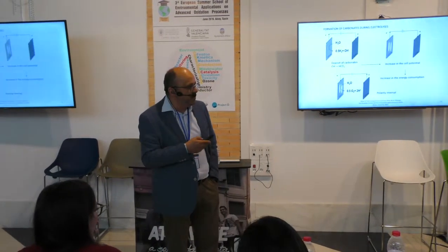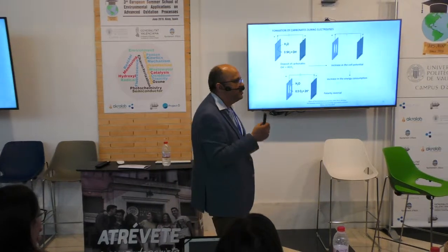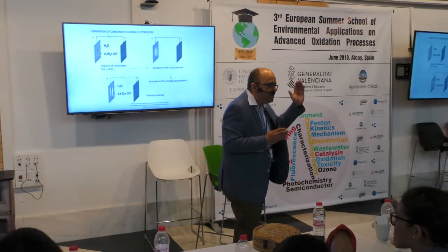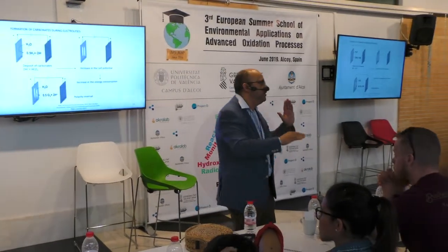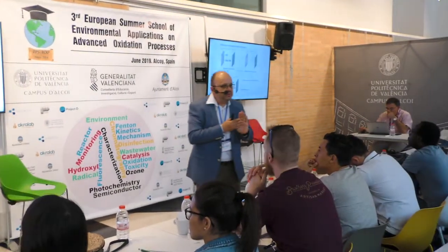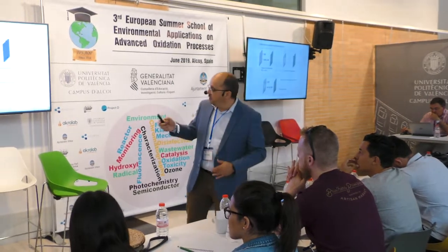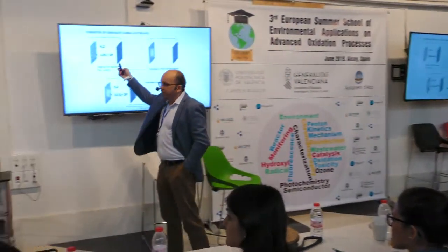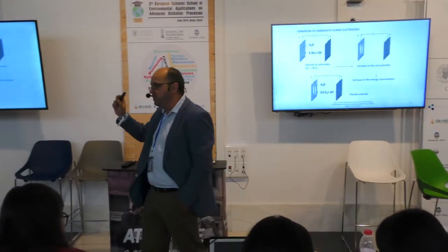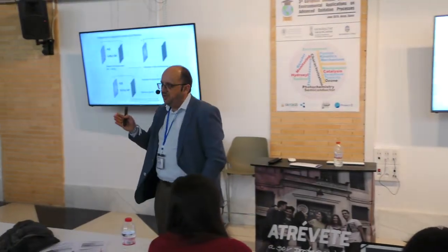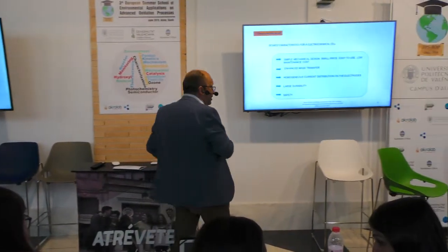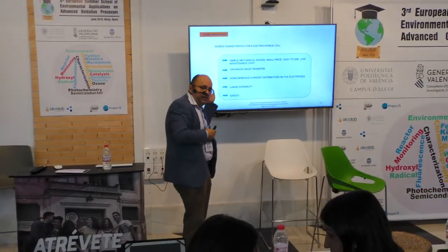And the main problem regarding the cathode is that we have to try to avoid the formation of carbonate deposits, because on the cathode you always have the reduction of water. And the reduction of water leads to the formation of hydrogen and also hydroxyl ions. And this can transform the bicarbonates contained in water into carbonates that form a deposit. And this can generate problems in electrolytic processes, okay? Well, this is about the electrodes.